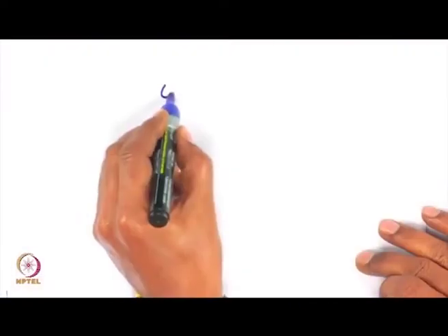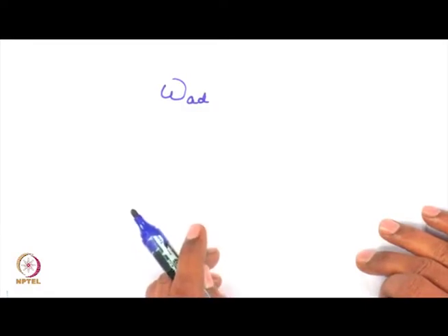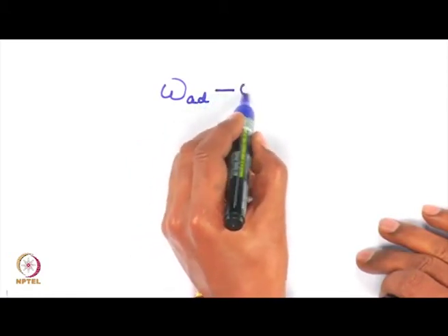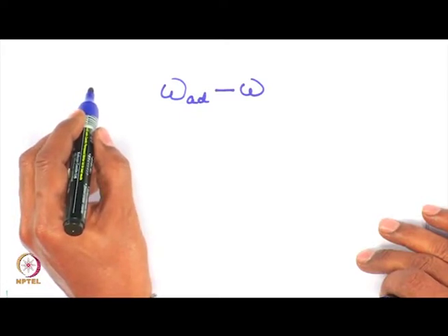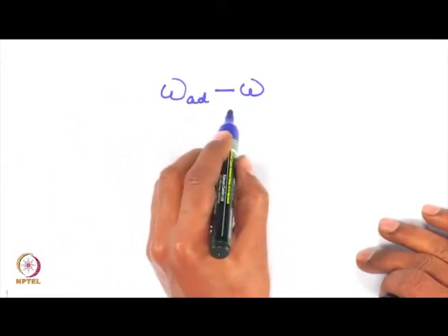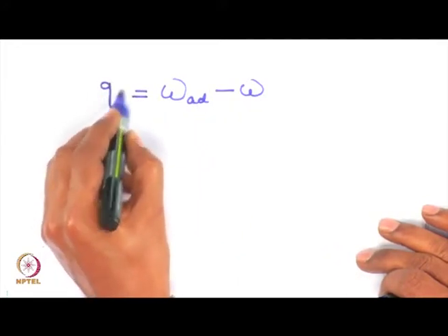So, earlier we had work under adiabatic conditions, and now if we remove the insulation, let us say the new work is W to get the same change, then this difference in the work is equal to the energy that has left the system, and that energy is heat.